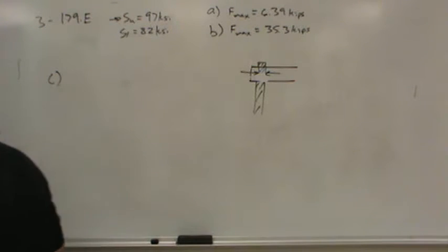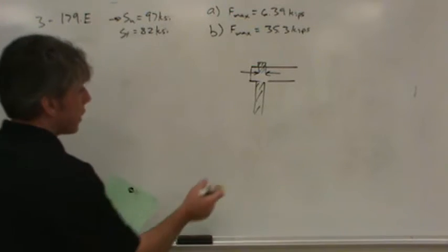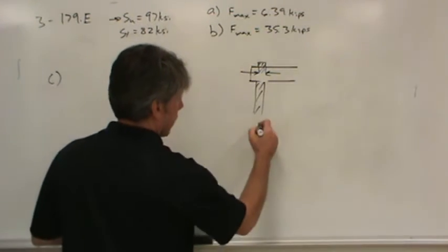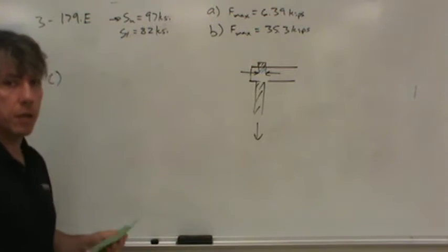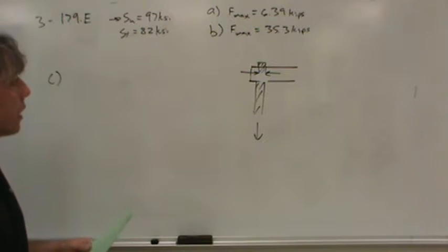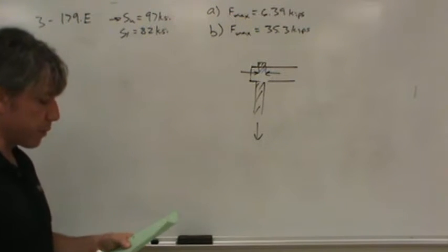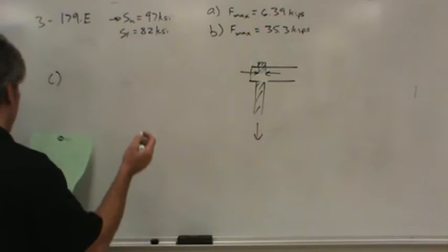If you look at the problem statement, it says, what about tension in the side plates? Well, these side plates are being pulled, right? There's force in the plates as well, so that's another place that this chain could fail. Now, there's more than just this, but for our purposes in learning the class, these are the three primary types of stresses we've talked about in this chapter.